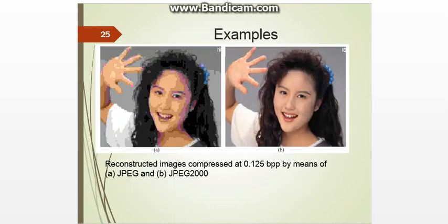The third one is the scalability. The scalable coding of the still image means the ability to achieve the coding of more than one quality and resolution simultaneously. The scalable image coding involves generating a coded representation in a manner which facilitates the derivation of images of more than one quality or resolution by scalable decoding. The bit stream scalability is the property of a bit stream that allows decoding of the appropriate subsets of the bit stream to generate a complete picture of required quality and resolution.